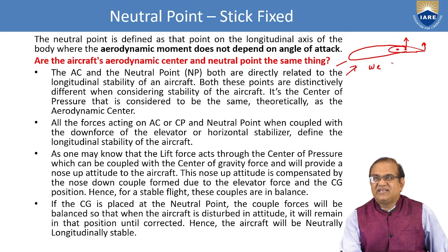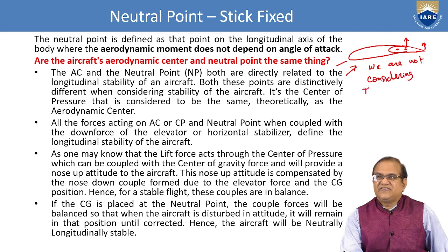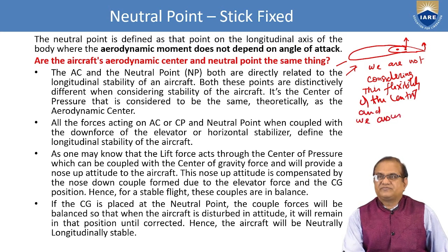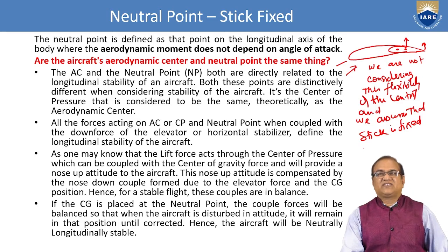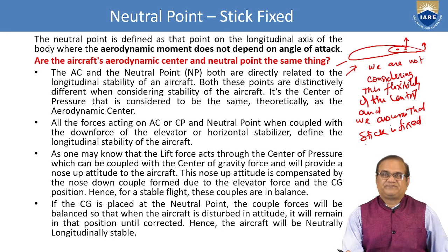We are not considering this flexibility of the control, and we assume that stick is fixed. In our whole cases, till the time we are not specifying especially that it is a stick free, all the cases which we are studying and we are deriving the equations of stability, all are for the stick fixed case. So this we have to understand first.